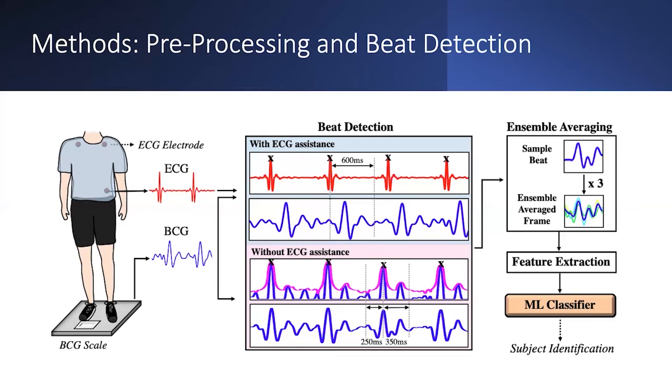as our reference. To detect the J peaks, the BCG portion where amplitude was greater than 0 was taken on the BCG signal, and the upper envelope was constructed. Basically, the local maxima points in this envelope corresponded to the J peaks.